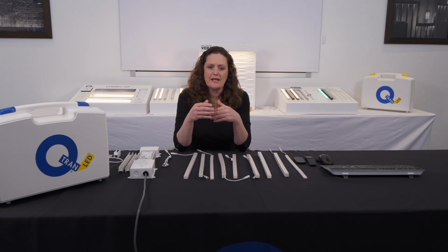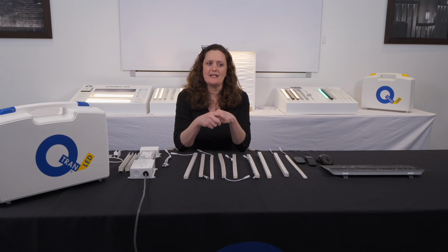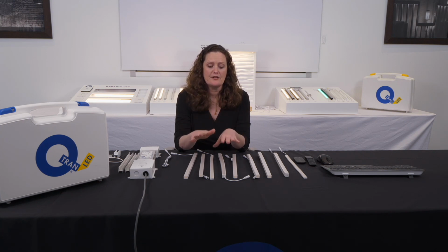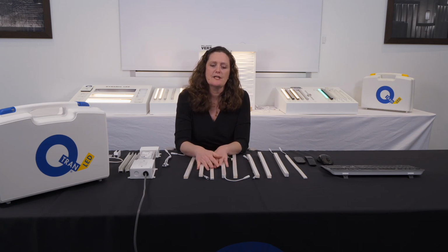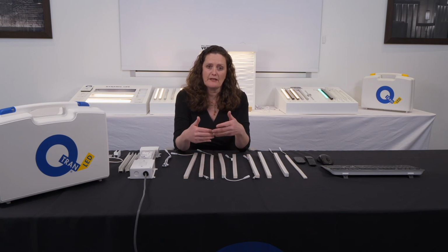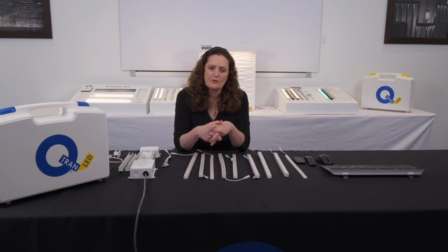However, that being said, your fixture length is usually dictated by what it is we are encapsulating and the cut points of the LED itself. And then we talk to you a lot about the nuance of your project and how direct view it is, what are your tolerances. There is a tolerance to the building of this fixture based on end caps, wire feeds, and the LED that's in there. So we really get into the details with you and what's priority for your project, length of light or length of fixture, and we also accommodate for or work out voltage drop issues.